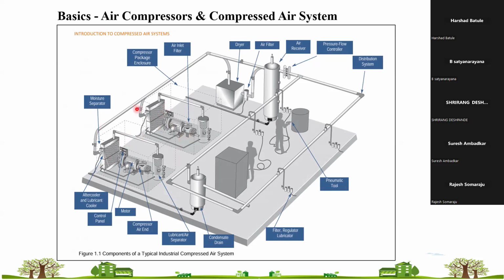So if we are running the 100 CFM compressor at base load and the 200 CFM compressor as peak load, on-off kind of thing, the unload power of the 200 CFM compressor is on the higher side. Your requirement is, let's say, 230 CFM. So 100 CFM is given by this, and 130 is given by this. So the load unload cycle will be there.